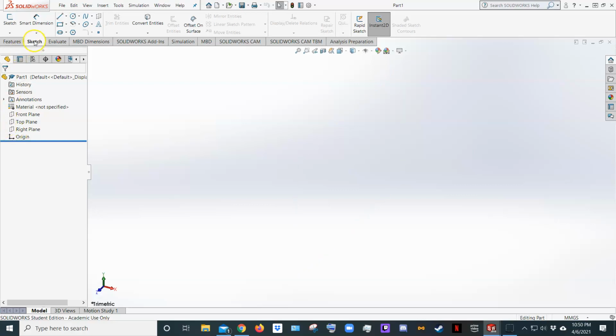Okay, now under the sketch command, you see that we've got sketch, which creates a new sketch or edits an existing sketch. We've got the ability to create a dimension for an object in our drawing. And then here is where we actually have our sketch tools. So the lines, circles, splines, which are curved continuous lines, rectangles from corner to corner, arcs, ellipses, straight slots, polygons, and fillets are all here available for you when you want to draw them.